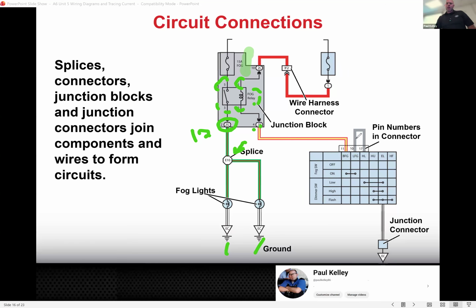If you wanted to tell if there was 12 volts at this wire, you would have to go to the male terminal based on that chevron. Get what I'm saying? Whereas if you wanted to know if you had 12 volts up here, you'd actually have to go to the female terminal on that chevron. See, because it doesn't go top to bottom when you get in the car. It goes any which way. You don't know which way is which.